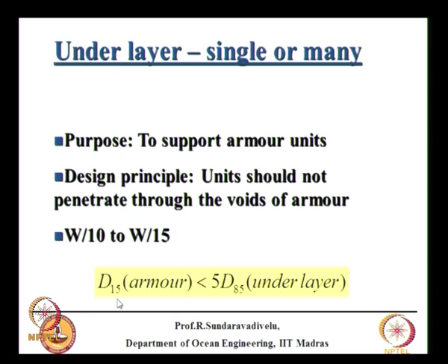Here we have given that D15 size of the armour unit should be less than 5 times D85 size of the underlayer. What is D15 and D85? Civil engineering students, not effective diameter.